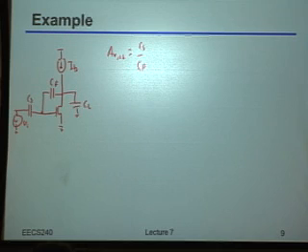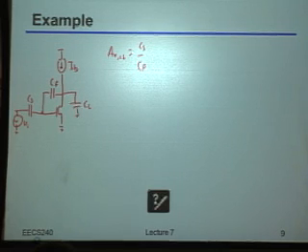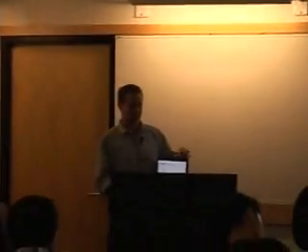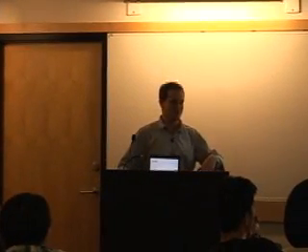Yeah, exactly. So remember, if you had just a normal op-amp circuit, that, if we go back, that's going to probably die. Okay, we'll come back to that. I'll just have to restart this, but we'll come back to it. But just while I'm restarting this, if you had essentially a normal op-amp circuit with resistive feedback, you would have said that basically the gain is just RF over RS, right?